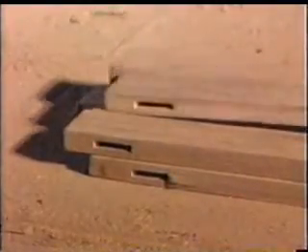The grooves are not cut through the entire depth, but remain short by 25 millimeter of the width of stile. Next, we come to the preparation of rails. In this, the rails are shaped by a tenoning machine.